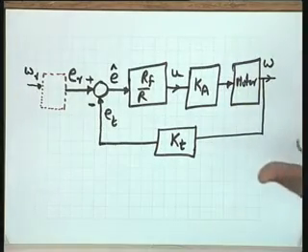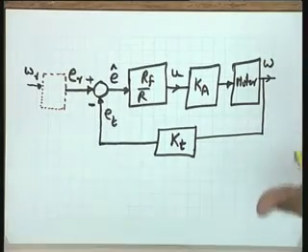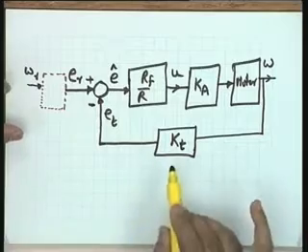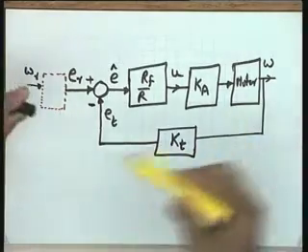Now, suppose you see, as I told you, that for the purpose of analysis and design, the unity feedback structure may be more convenient. In that particular case, I will like to transform this to a unity feedback structure without sacrificing the information contained in it. So, naturally I like that the basic equation remain the same. If the basic equations remain the same, in that particular case, you please note that this particular block should contain kT, and it has to contain kT.